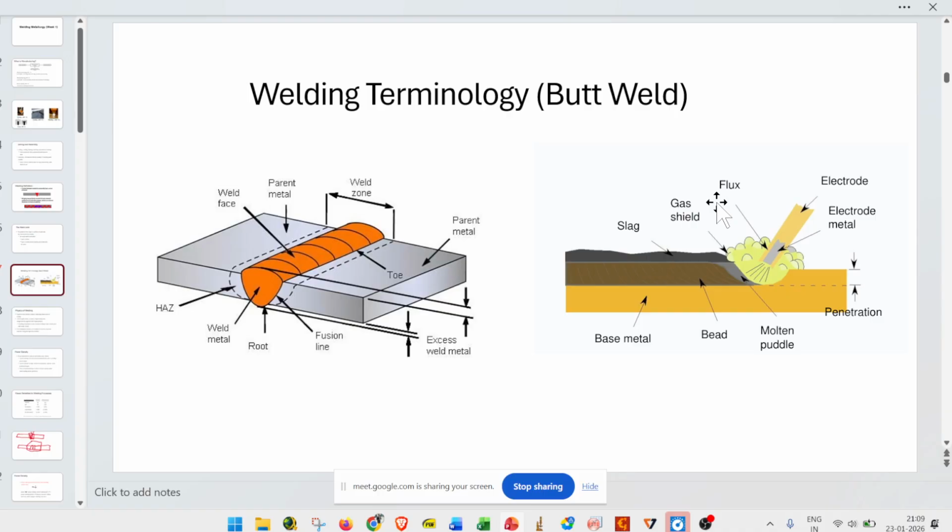Why we have to provide this is that when we deal with metals, what we want to avoid the most is oxidation. Once oxide is formed in the bulk material, the material strength drastically reduces, because oxide does not form a crystalline structure. It becomes brittle and makes a weak part in any metal component. So we want to avoid any oxidation.